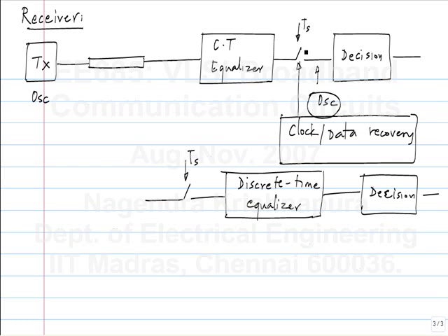So here you have the sampling followed by the equalizer. So even if the sampling wasn't working properly, you can have the correct signal here, and roughly speaking the clock and data recovery circuit will work independently of the equalizer. Whereas in this case, if the samples were incorrect to start with, your equalizer output will be bad, but the clock and data recovery circuit may be dependent on the output of the equalizer. In this case, you have some kind of chicken and egg problem.